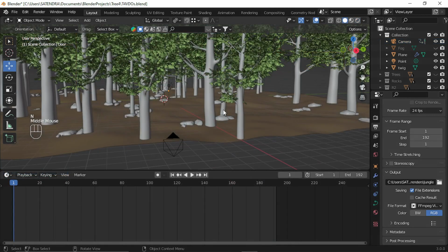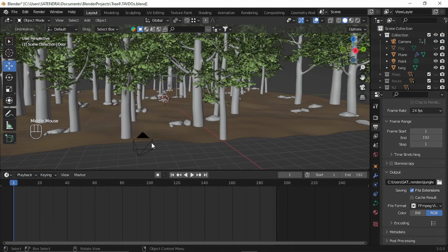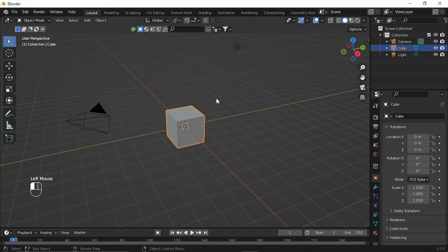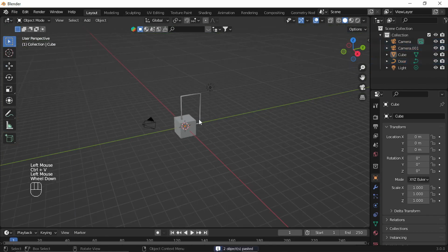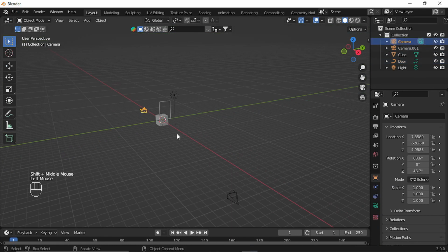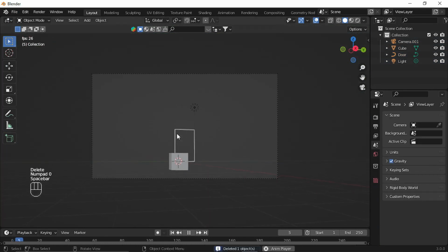Now let's create our second scene, the desert scene. So I'm going to use the same camera movement. So select your camera and also select the portal gate just for the reference. So shift select this and Control C to copy it. Let's create another file and Control V. So again, you can delete your primary camera here and you can check the existing camera working.